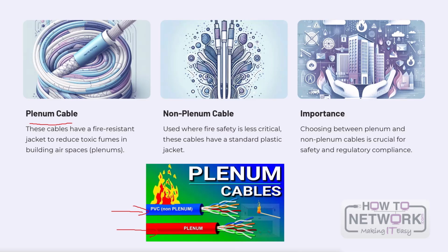Now, the non-plenum cable, in contrast, utilizes a standard plastic jacket suitable for areas with less stringent fire safety requirements. While it may not offer the same fire retardant properties as plenum cable, it's often a more cost-effective option for installations where fire risk is lower, like residential settings or non-critical commercial spaces.